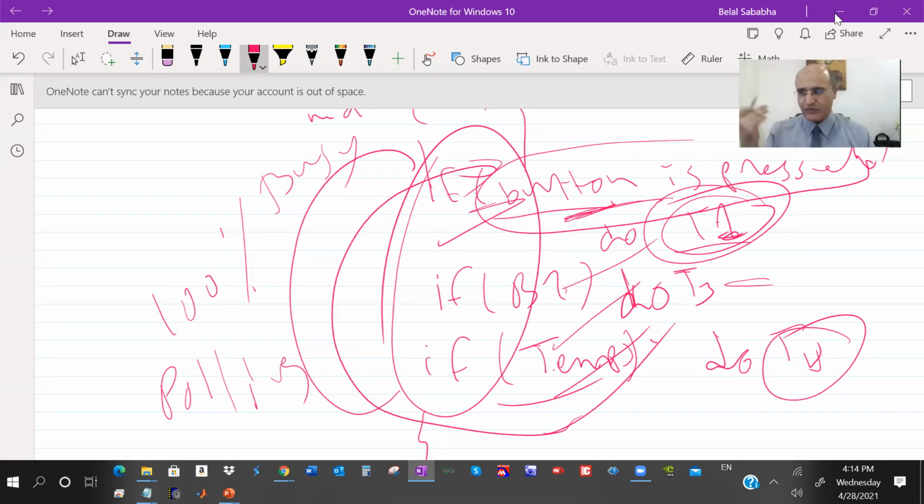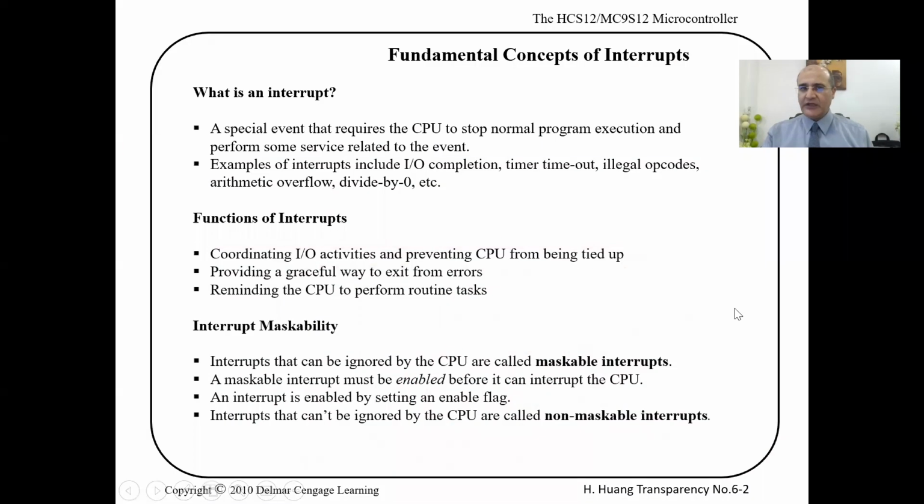And in embedded systems, we're usually talking about real-time system controllers, code to control real-life stuff. It's not allowed that you turn on the AC and it takes a delay of 5 seconds, then it turns on. This is not acceptable. You start your car, then you push a button on your dashboard, and a delay happens because of other routine tasks that can wait. From here, the concept of polling is not acceptable in real-timeness.